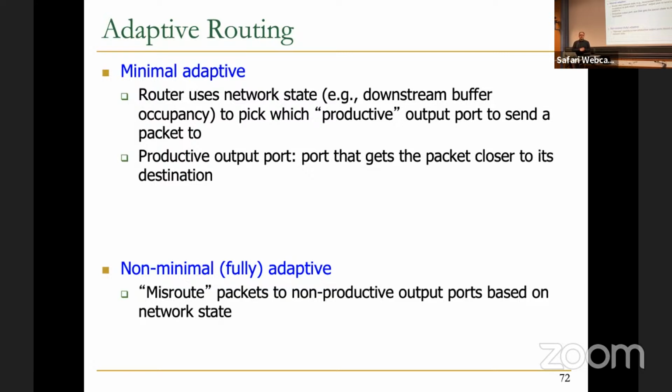So yeah, hot potato, essentially that's the routing algorithm. And it's actually used for bufferless NoC because you cannot wait, right? This packet is a hot potato for you, and you need to just pass it. And hopefully you pass it to the destination, but you can also misroute it sometimes.